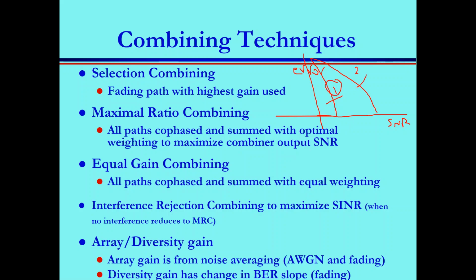One has more diversity. The effect of diversity on your bit error rate is that it pushes the bit error rate curve towards the y-axis, which means you can get lower error rates at low SNRs. This is what it means: at low SNRs you get better bit error rate. Why do I need a low bit error rate? Because this improves the reliability of my system, and reliability is one of the critical performance metrics in any communication system.